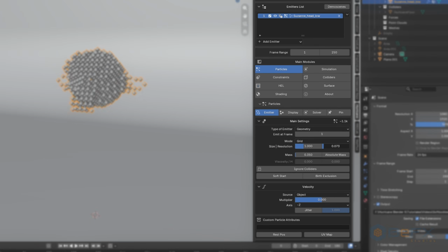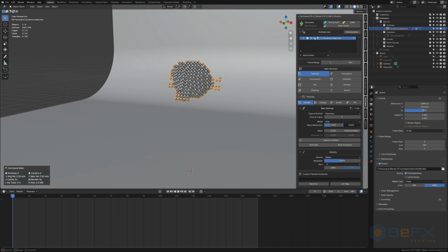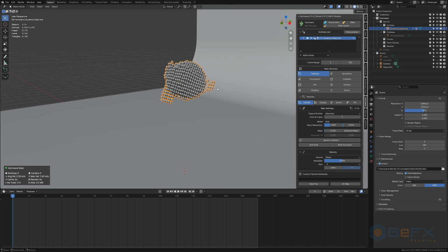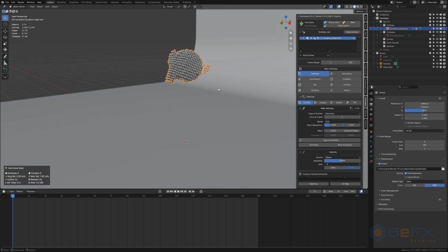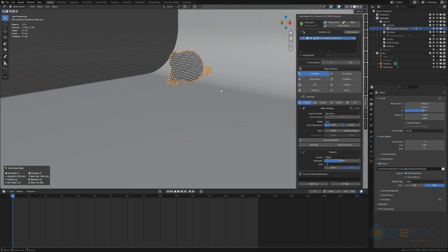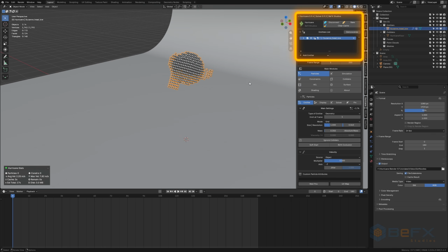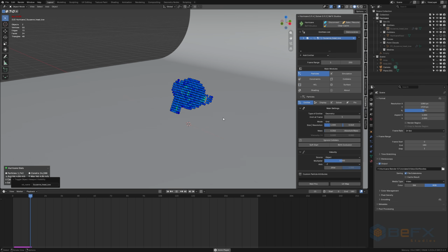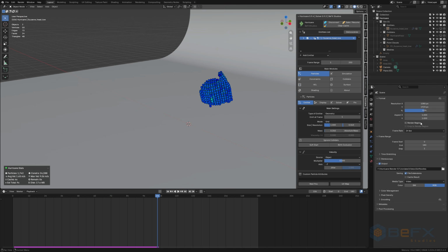We set a balanced grid density, neither too high nor overly low, allowing the geometry to deform with sufficient flexibility without generating an excessive number of constraints that would slow down computation. Once resolution is configured, we hide the emitter and play the simulation. We immediately notice that the initial result is far from ideal. Particle interpenetration occurs and the object bounces continuously.